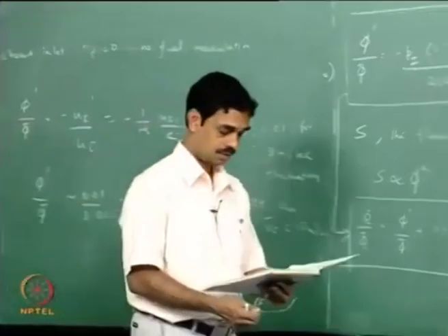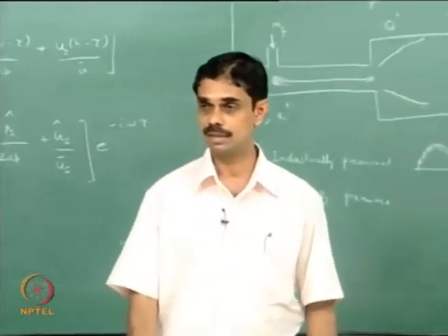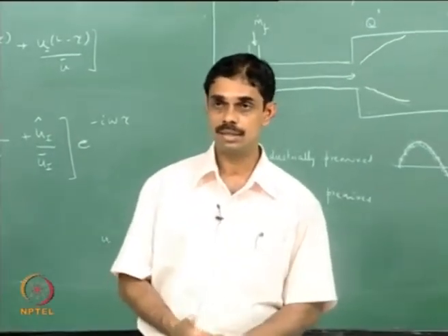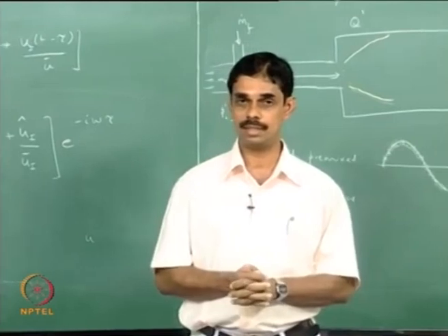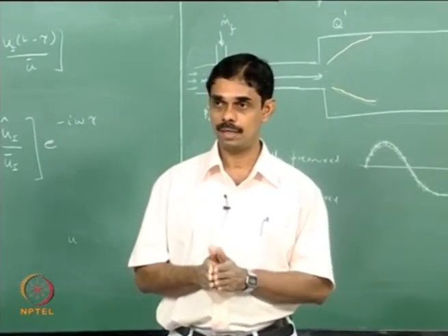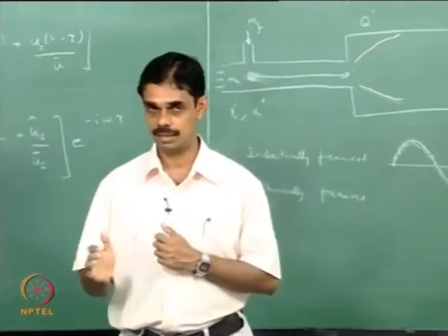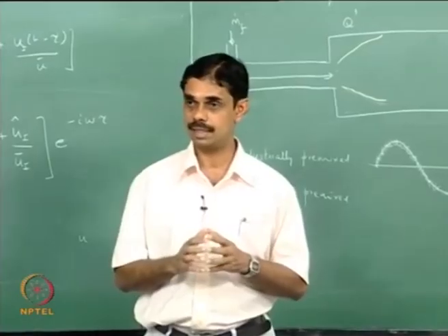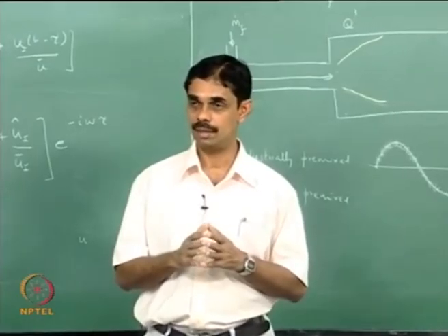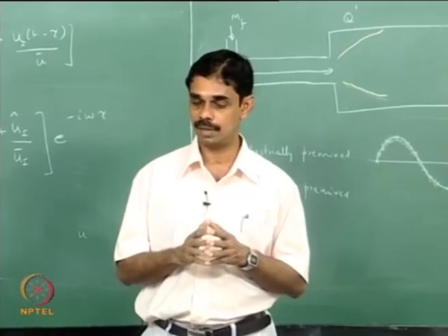There is one more issue involved here other than this instability leading to oscillations. When you have very large amplitude oscillations and you are at the lean blowout, whether the flame stays or not depends on whether locally somewhere the radicals are there and the flame velocity matches the flow velocity, but if you have very large amplitude oscillations, the flame may blow out.